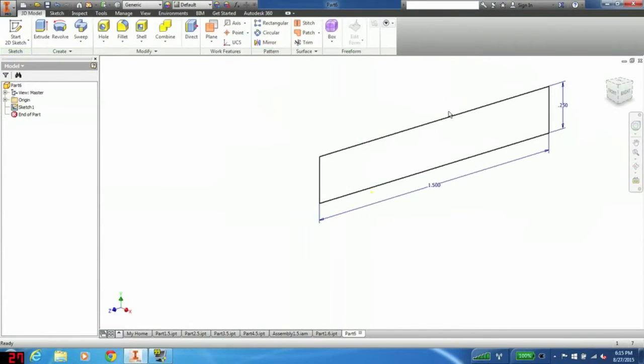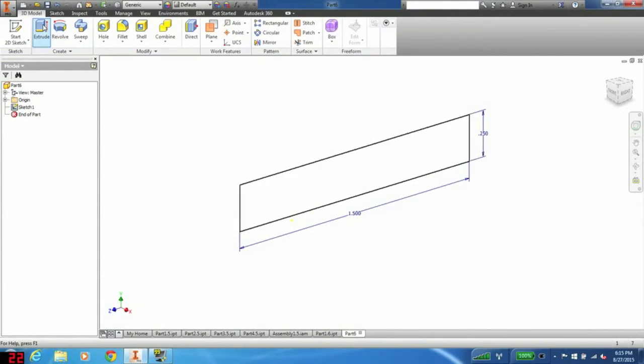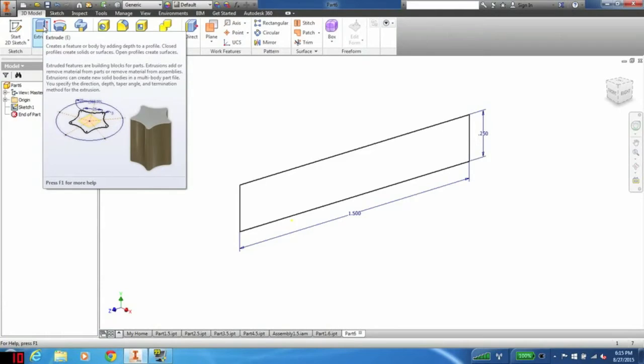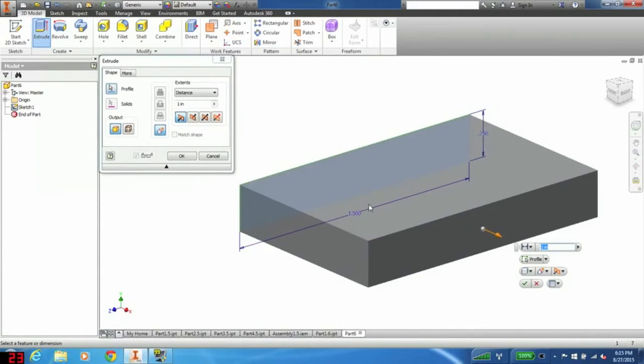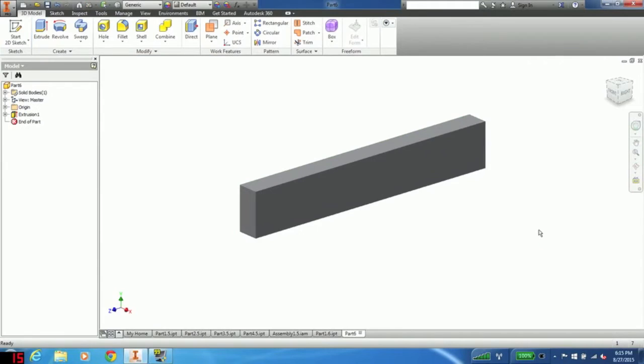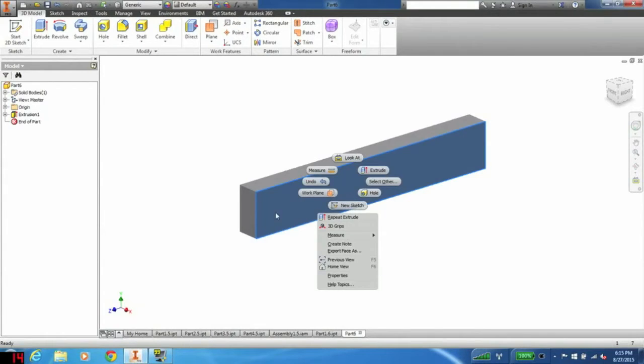We're not going to put 2 holes in because we need them to come out of the shape rather than be turned into holes going through the shape. So now we're going to take the thickness, which is 1/8, and now we need to create the pegs, the cylinders. So we're going to create a new sketch on top of this.